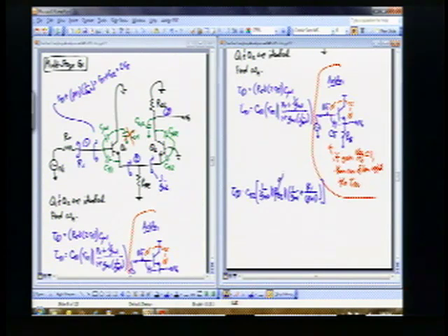I can neglect REE usually because REE is usually very large. Okay, so I'll say REE. That's where I'm neglecting that. Okay, so now I've got just one more of these to do. I've handled all the capacitors except for one now. That's C mu 2, actually two of them. I have C mu 2 and CCS2. They're both tied to this node 3.